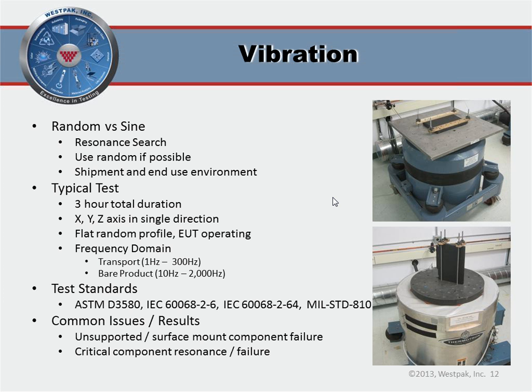For the first 10 years of Westpak's existence, one of our primary things that we did was to fix vibration problems in large package systems, where you have the package resonating at the same frequency as the product, or the structural resonance of the product, which is typically in the same range that the vehicles are going to input. So don't ignore vibration. It's a killer, and it's going to exist.